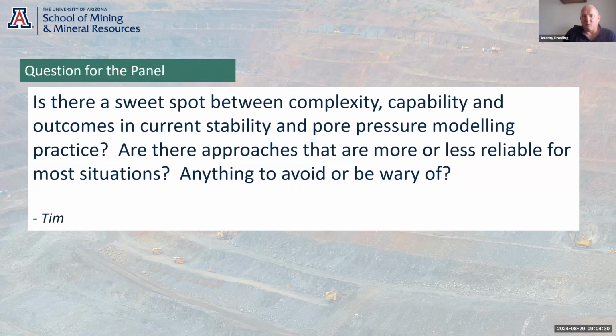So I think that workflow, the use of simple groundwater inputs to the geotechnical models, and a really good monitoring program is much better than trying to do a lot of really complex, quote unquote, pore pressure modeling that is then put into the design analysis.